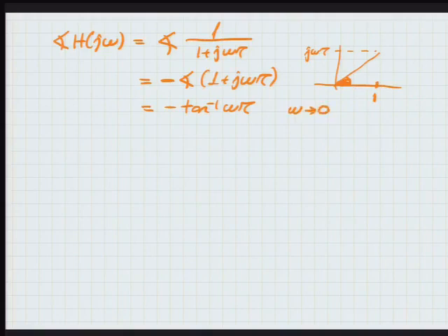When omega goes to 0, what would that be? 0 degrees. And when omega goes to infinity, you'll get 90 degrees. Today I'll call them 90, 100 just to make it more accessible, I guess. So when you plot this on the logarithmic scale, rather than like an inverse tangent, it will actually look more straight, like 0 and 90 degrees. Actually, negative 90 degrees, keep the sign. And more like negative 90 degrees, and a sharp transition in between.